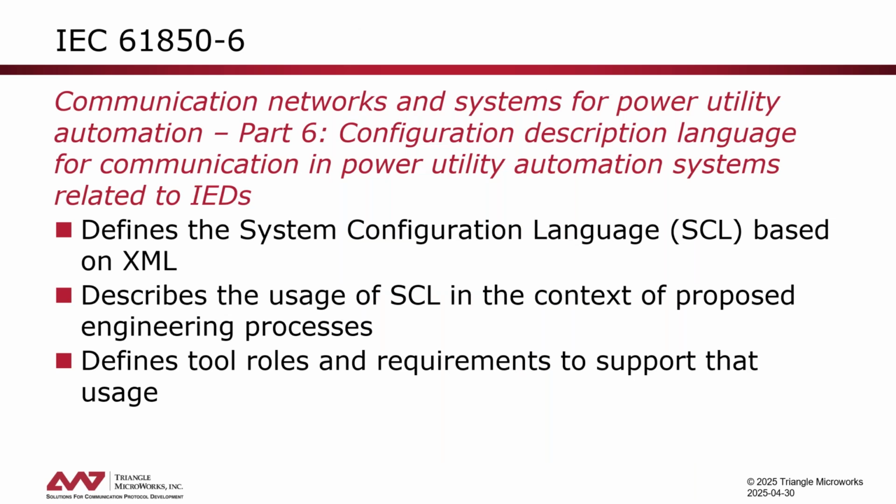Part 6 basically describes a language for how we can create files that describe the configuration of our system or of our device. It's based on XML, a standard from the web industry. It also defines processes for how to use these files for the engineering of a system. It defines tools, tool roles, and requirements to support this usage.